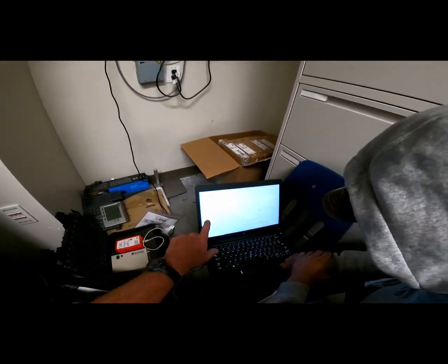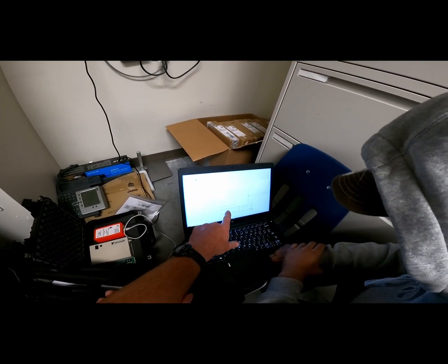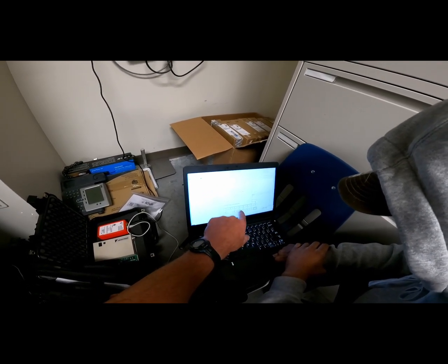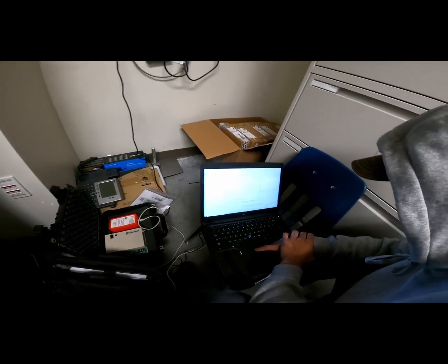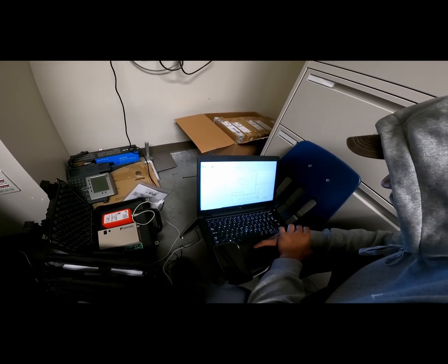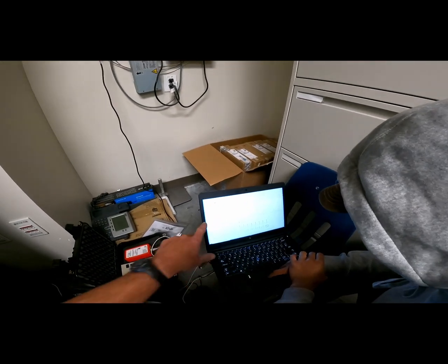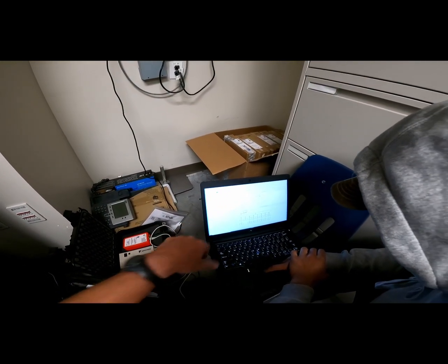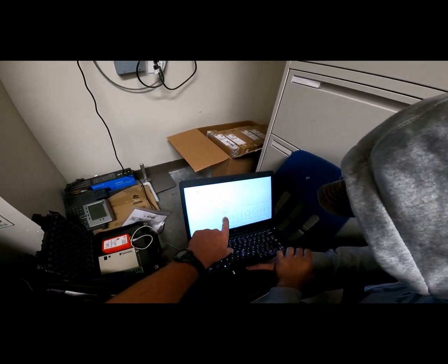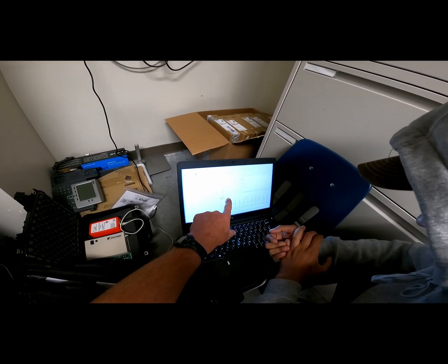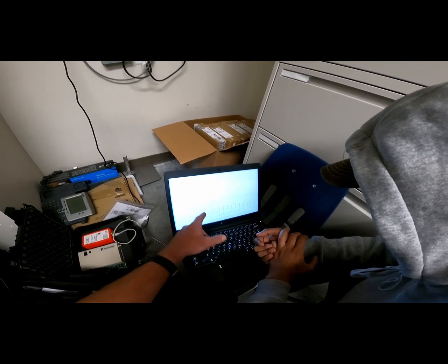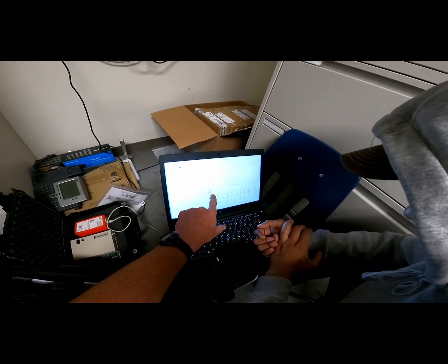But as you can see down here, it's pulled up one of these outdoor units. And you'll see here in a second, it'll show the branch box, the indoor coils, and the remotes that control them. And those are essentially just thermostats. Okay, so just hover over address 51. It shows that at address 51, you've got an outdoor leader, an outdoor follower tied to it, and they're piped in parallel. Their two pipes come into a branch controller.